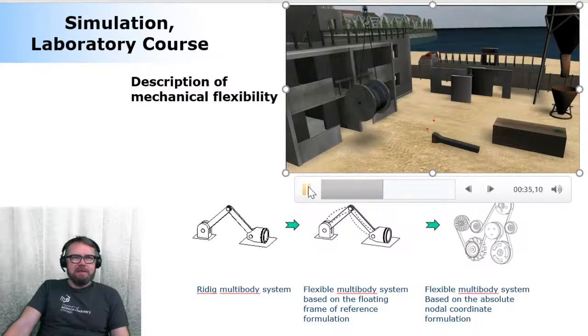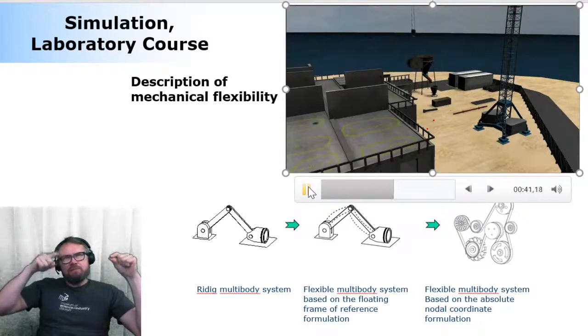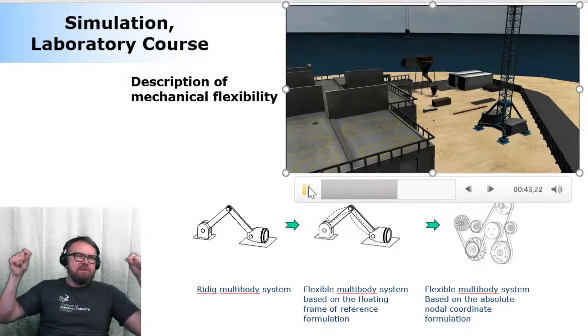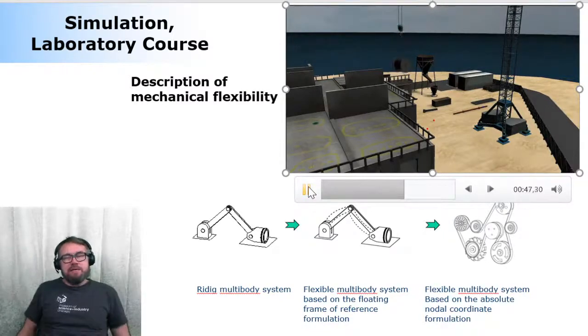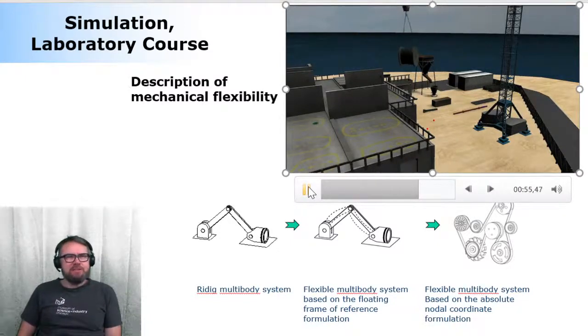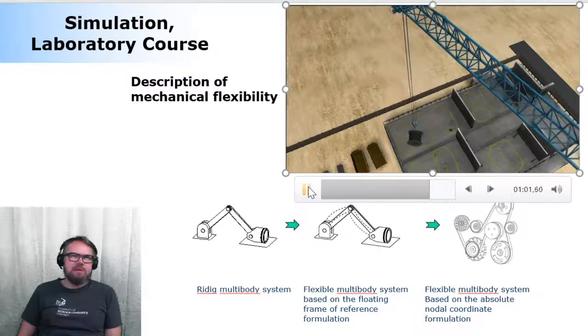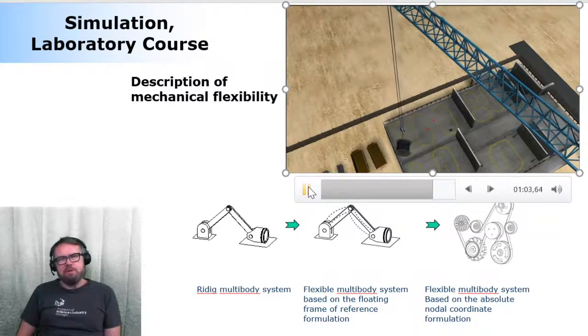That effect means that if there's a cable without any pretension, its transverse vibration frequency is very low. Once you tighten it, the frequency will change. This is what you can see when you play a guitar: you can tune the wires, and this is the way you can make them sound in a particular way. You can see this also in cranes and in cables in general. So we will look at this kind of stuff.